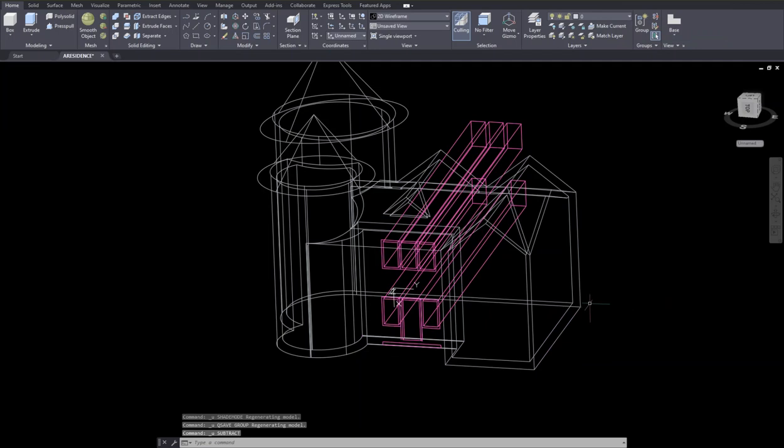Okay, so we are back in here. All right. Are you with me so far? So Control Z, so what happened is that I extruded the back side, but the front side did not extrude properly. And so this is not good enough for me. So what I'd like to do is move the extrusions forward a little bit, okay? Or at least press pull the extrusions.